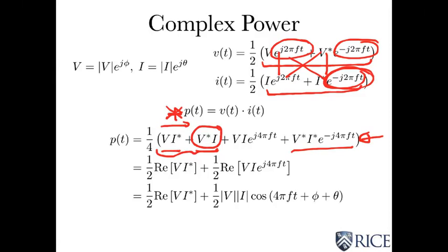All right, because the conjugate of a product is the product of the conjugate. V conjugate, the conjugate of V is V conjugate, and the conjugate of I conjugate is just I. Get it back again. Same thing happens out here. This is the conjugate of that. So those are real parts. And notice, because you multiply by a quarter, you have to put a half factor in to get the real part in the final answer.